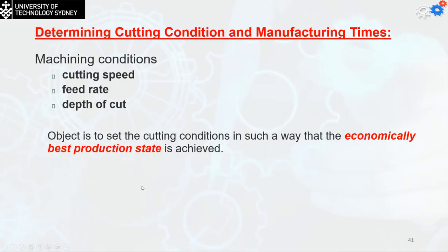The main thing in one of the planning processes we have for the manufacturing process is we usually try to get the optimized speed of the cutting in the machine operation that will result in the best tool life. Now, why are we doing that? Because simply we don't want to stop the manufacturing process each time to change the cutting tool. This will be a waste of time during the manufacturing process, and this will lead to the reduction in the production rate in the manufacturing processes.